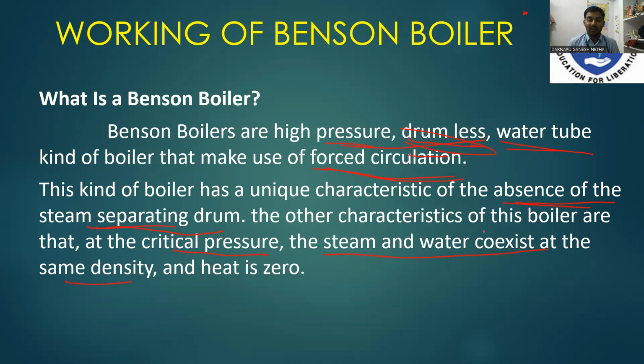The other characteristics of the boiler are that it operates at critical pressure, water and steam exist at the same density, and latent heat is zero in this boiler. I repeat, in the Benson boiler, water and steam exist at the same density, and latent heat is zero.